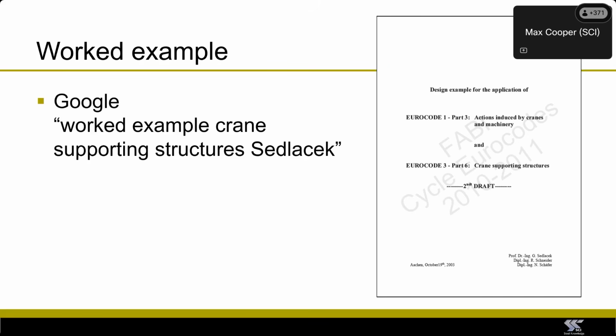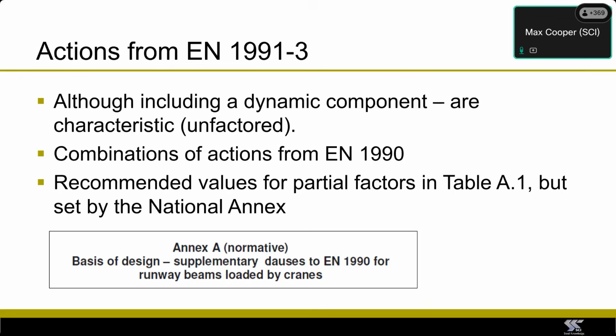If you're interested, or if you're doing this, we would recommend this worked example shown on screen. If you Google worked example crane supporting structures by Sedlacek, you'll find this, and we would suggest that this will go through all of the loads, all the different dynamic factors, and is helpful to have by your side, whether you are looking at crane actions for the first time, or indeed the 10th.